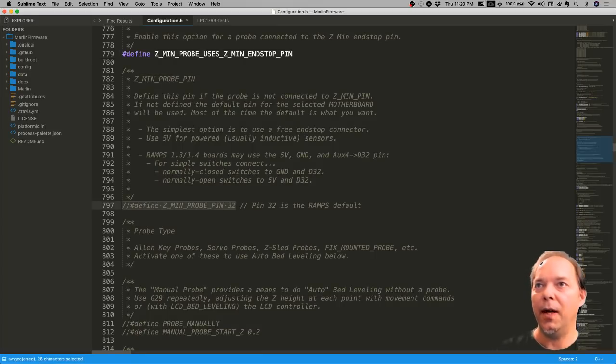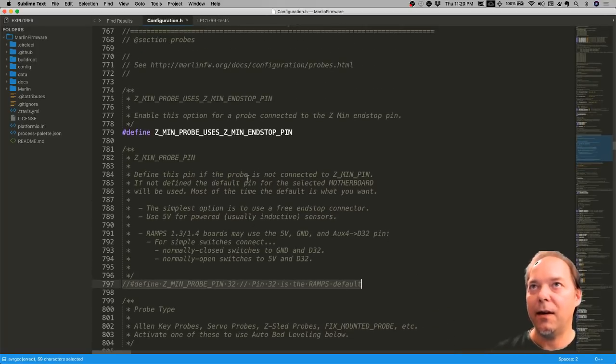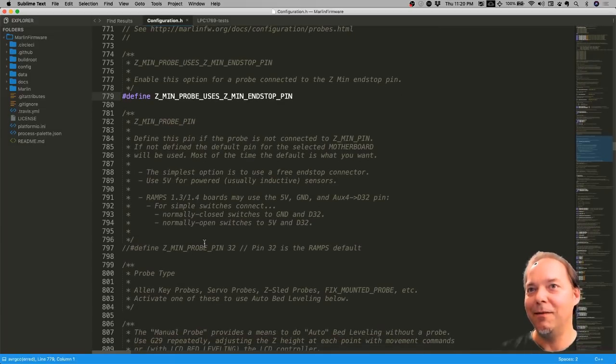And now we put the override basically here. It's like having the other option in a way, but it's not meant to be a one-to-one replacement so much as, now that we've changed it, we might as well put the default here and keep it here. So if you don't define this, you'll still get a Zmin probe pin from your RAMPS file if you've defined a probe type.